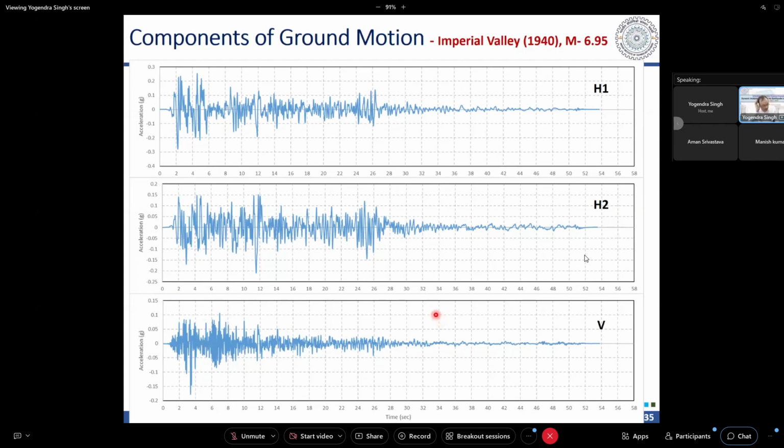So when we are using time history, sometimes we use artificial time history. And what people do, if they have to perform biaxial analysis under two ground motions, whatever is given in the x direction, they apply in the y direction. That should not be done. The ground motions are naturally uncorrelated, and the ground motion in H1 should be uncorrelated with H2, and it should be uncorrelated with V, the vertical component of ground motion. The same ground motion scaled by different factors cannot or should not be used. That will give highly conservative results.